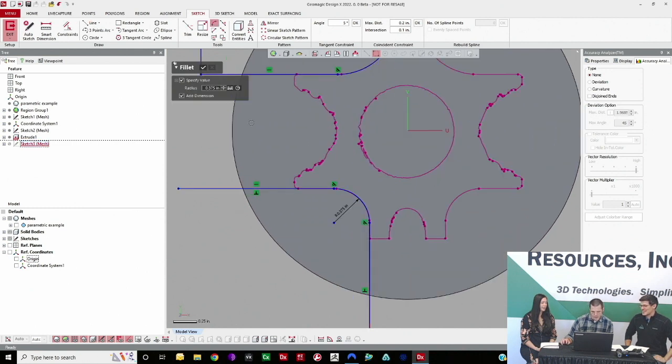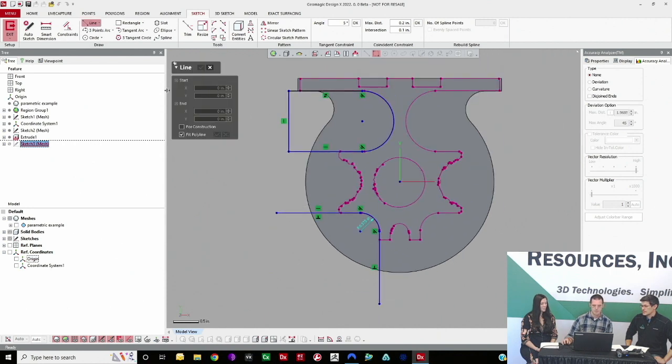I'm just adding some fillets. I got lucky there. There's a 375 fillet, but if I didn't have 375 set, what you could do, this is kind of cool. Inside of Design X, you can play with fillets by clicking and holding and dragging. You can see you can change the size of the fillet and get it close. And I'm at 3714. I'll just make this a 375. Close this one off as well.